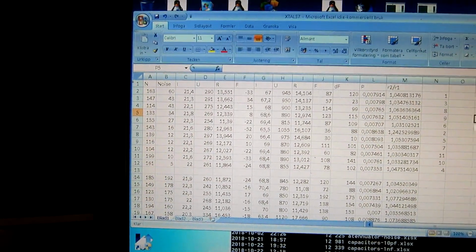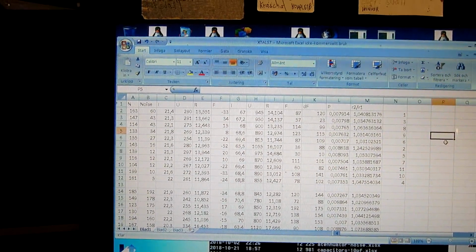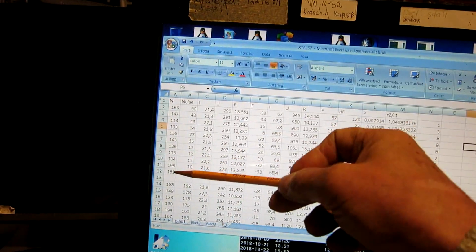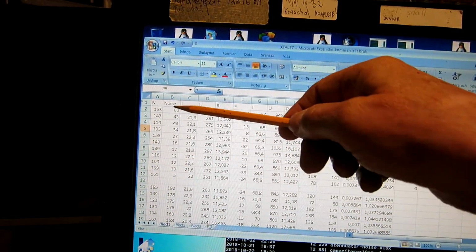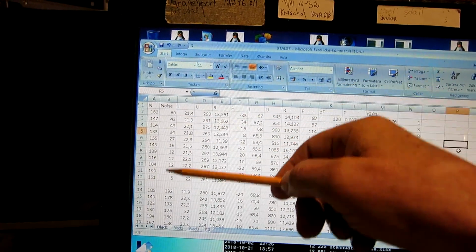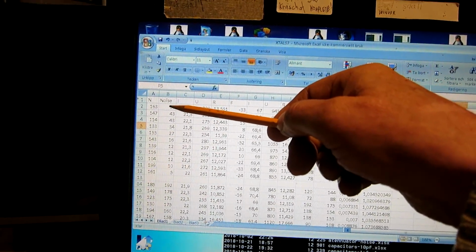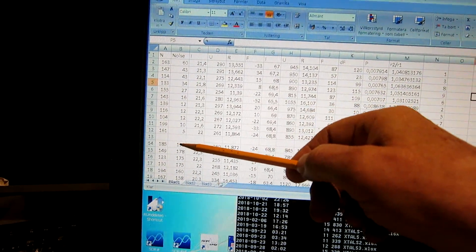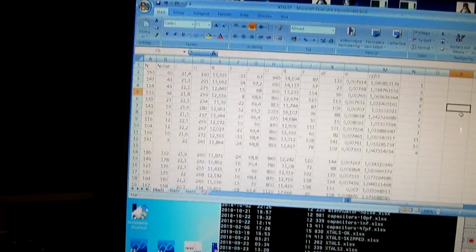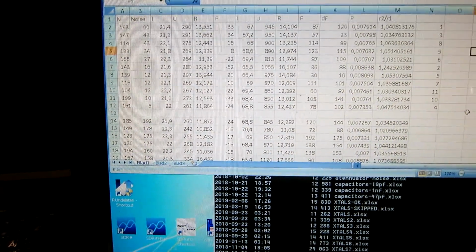Before I started to build oscillators and filters and other things with these crystals, I measured their characteristics. And here are the ones I have now measured, sorted in descending order of noise, which means the maximum current I could send through the crystals before they started to misbehave. And here are all the crystals I had. The best ones start at 192, and they are mounted in some equipment, so I don't have them to study now.